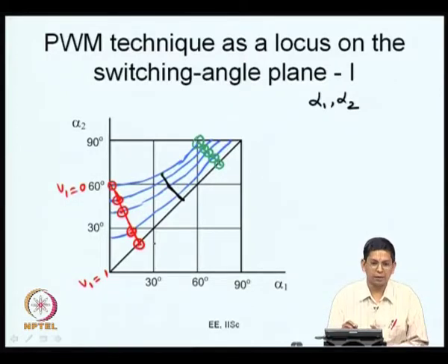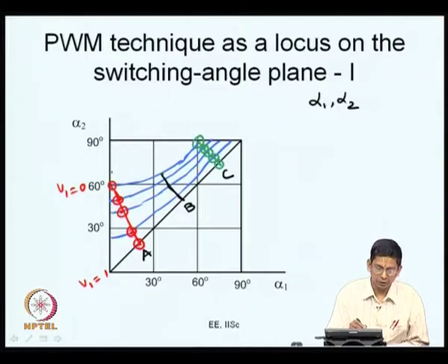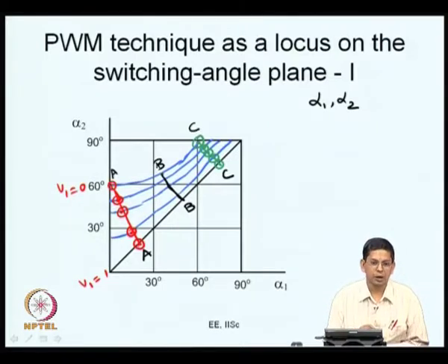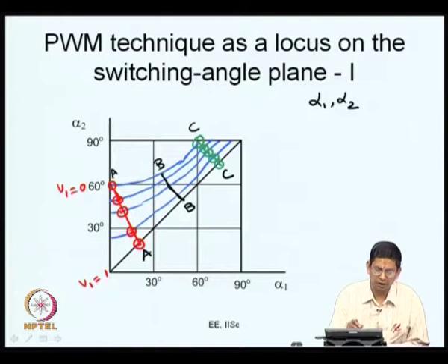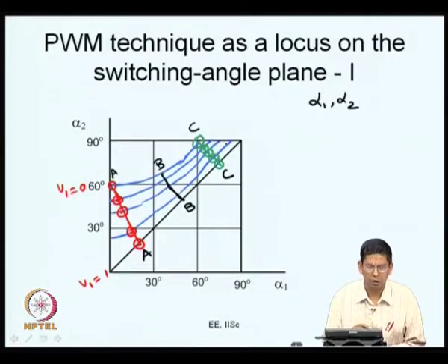Now, along this curve, which is good, which is bad, we need to look at the harmonic contents. Already we have seen along this, for example, let us just call these 3 curves A, B and C. We have already seen A is good as far as 0 voltage is concerned. C is also good as far as 0 voltage is concerned, but B is not so good. But this is at 0 voltage, and this knowledge can be extended to a small amount of fundamental voltages. If B is going to produce a very high amount of harmonics at V1 equal to 0, what it means is basically for small values of V1 like 2% or 5% or 10%, you can still expect the harmonics to be very high, that is with B. If A and C are expected to produce low amount of harmonics at 0, they can be expected to produce low amount of harmonics at small amounts of fundamental voltages also. We will be comparing A and C sometime later, but these are just some examples of PWM techniques which I wanted to give now. There could also be other examples.